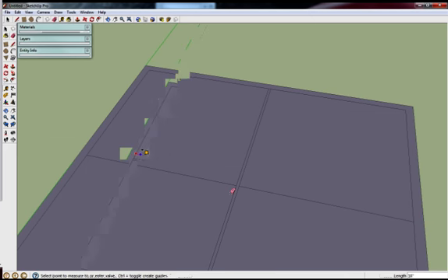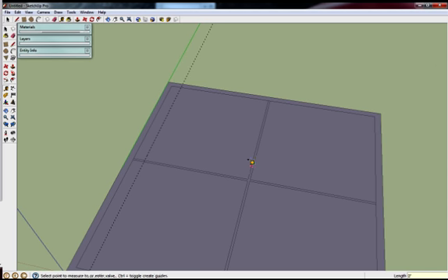Let's install some doorways. Using the tape measure tool, the T key, lay out 2 doorways, 2 feet away from each wall. Place 2 more lines to complete the openings, making them 3 feet wide. Using the guidelines, draw out the openings. Take the eraser tool and erase the guidelines and the lines between the doors.